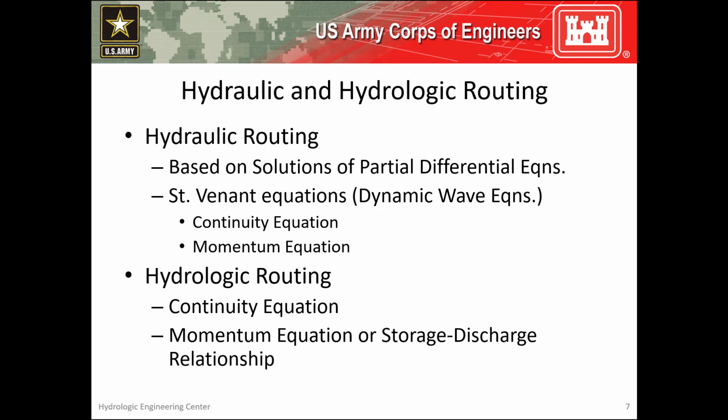Hydraulic routing techniques are based on the solution of partial differential equations which govern unsteady open channel flow. These equations are often referred to as the St. Venant or dynamic wave equations. Hydrologic routing routines employ the continuity equation and either simplified forms of the momentum equation or very simplified relationships between storage within the reach and discharge at the outlet as a replacement for the momentum equation.